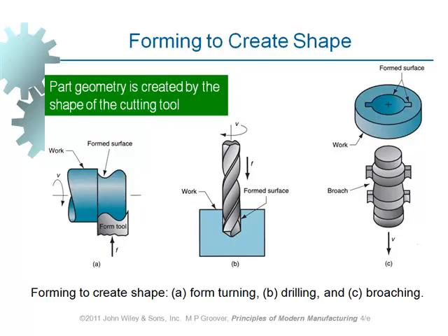Here, again, this time it's the cutting tool which is rotating, it's the drilling process, and the part is stationary. And here, it's the workpiece which is stationary, and the cutter passes through it. This is called broaching. You ask me what broaching is, right? This is the broaching process.